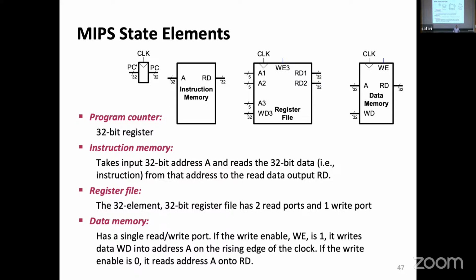This is why you want to have a specialized register file that manages two reads and one write in the same cycle. It's a luxury, to be sure, but it is doable. And we already saw that, if you were to write down the code of it, it's not that difficult. Then we have a data memory. Now, the expectation for the data memory is to hold hundreds and thousands and millions of data words. So this is the thing that carries the bulk of your operation.